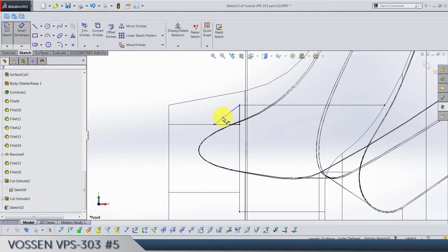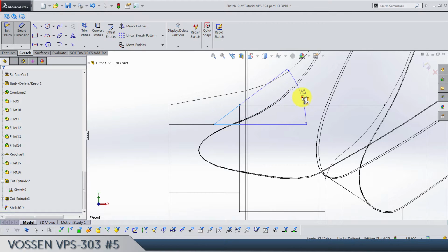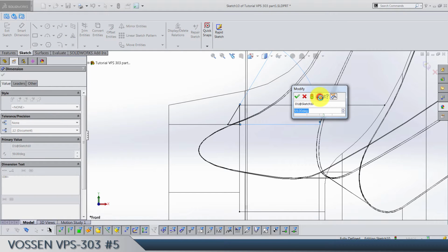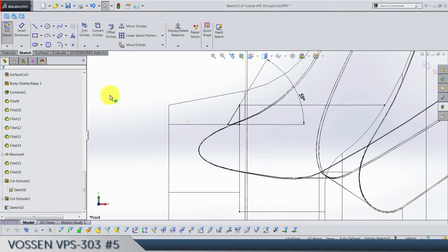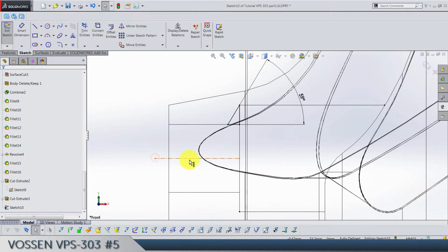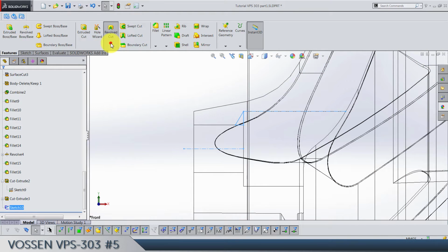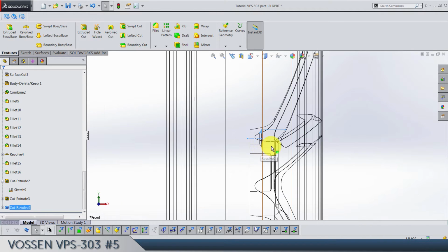The only thing we need here is angle of 59, sorry, 118 by 2, yeah, 59. And let's also make a center line here. You see the midpoint of this edge. Okay, exit the sketch and do revolved cut. Exit this one, of course. Click enter, and that's it.